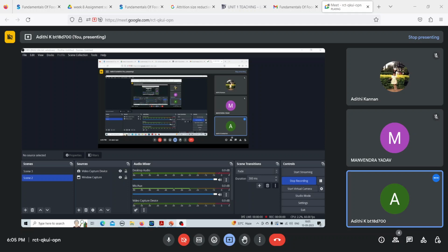So 0.45 in millimeters, and you have 3500 micrometer as the size of your feed. That again I am converting into millimeters, which is 3.5. So when I substitute the values and calculate, I get P is equal to 0.21 kilowatt.